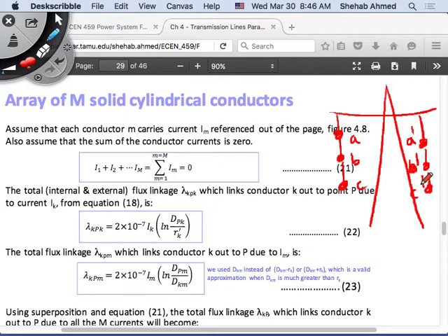The benefit of double circuit towers is that I need less tower space to carry two circuits, and it gives me redundancy. If one circuit fails, I can use the other circuit to feed the loads, for example, if it goes to a similar location.